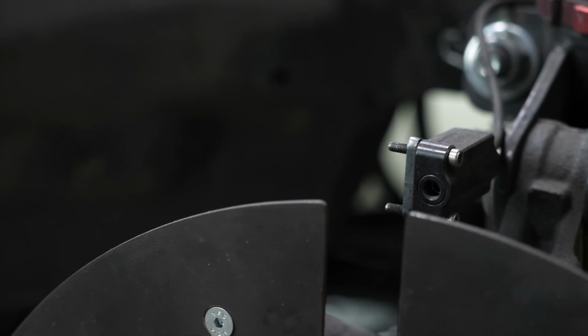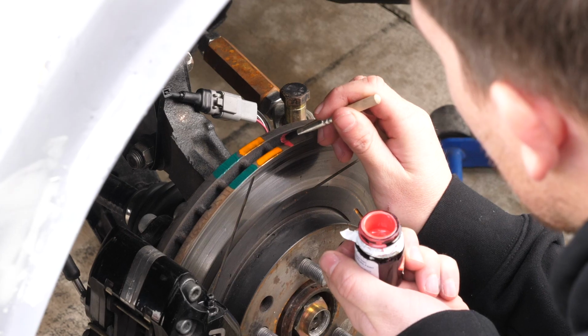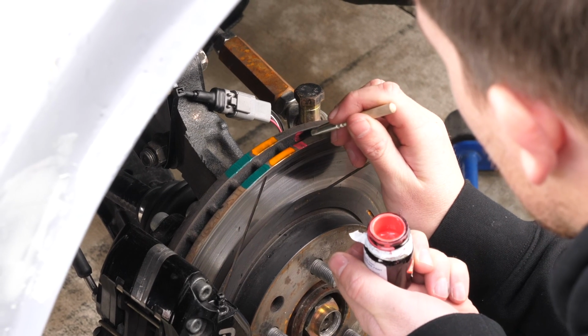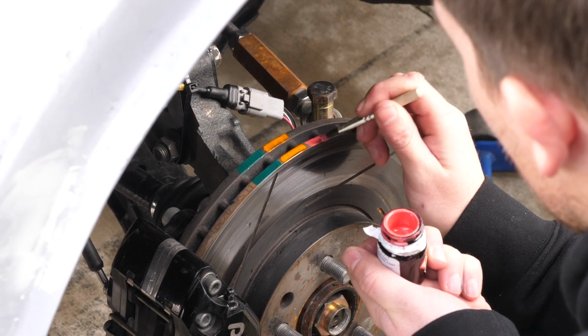We can use data from temperature sensors or other methods like brake temperature paint to determine the operating temperature of our brake system, and this can also be tuned by modifying the brake ducting. We'll be coming back to cover tuning brake temperatures in an upcoming module, so don't worry too much about this aspect for now.